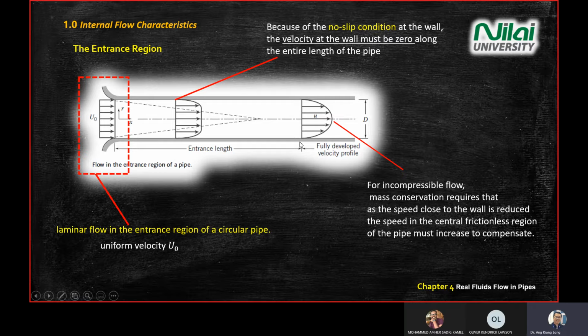What I mean by boundary condition is, at a certain location, what is the u value? So a very direct boundary condition is that at the wall here, your u equals 0. At the center of the pipe here, your u is maximum. Later, we will have an equation to derive this one.